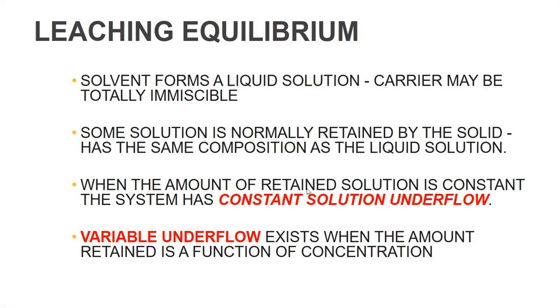The carrier solid, what is meant here is the carrier solid of your solute, should be totally immiscible with this given solvent. Some solution is normally retained by the solid and has the same composition as the liquid solution. This refers to the slurry, wherein you have solids which still have solution remaining on them.